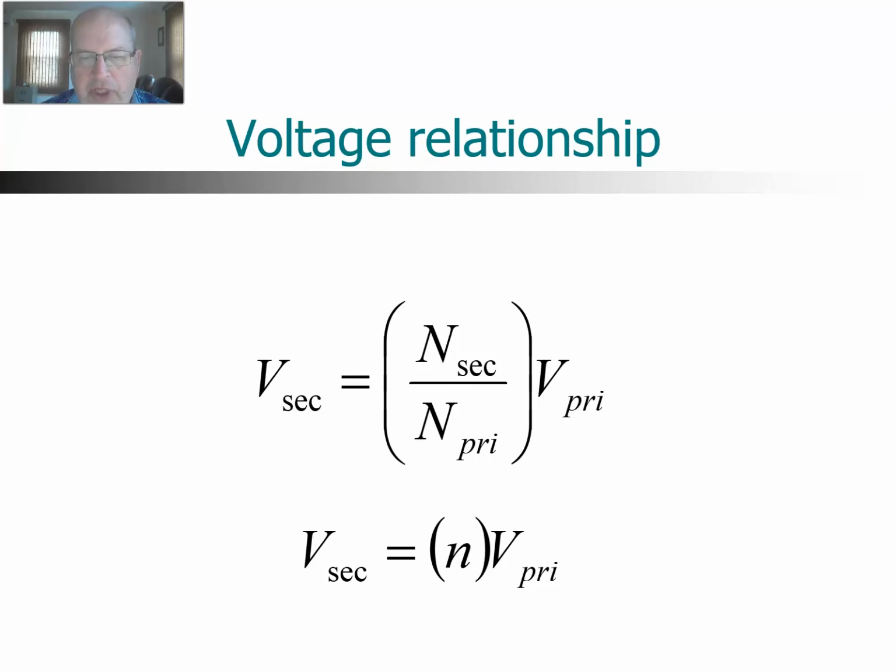By giving the voltages, it also gives you some additional information about the voltage capability of both windings, because when these transformers are constructed, you want to have the coils very, very close together. So you want to have very thin insulation. So as a result, the voltage rating of that insulation is very, very important. And by giving the voltage rating of both the primary and secondary, we are in turn giving the turns ratio.